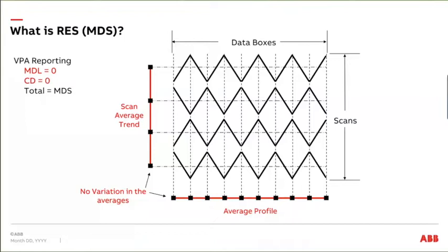If your real paper looked like this, please call us; you've got something really bad happening. But from a visual interpretation, you can see that the MD and the CD average to 0, yet there's a lot of variability. That variability is what we call MDS. That's the residual: the stuff left over in the sheet that gets washed out in the average.